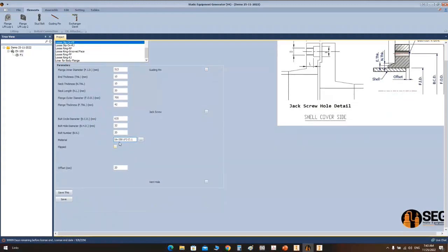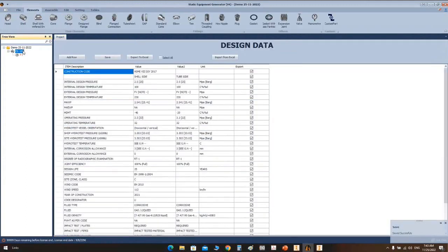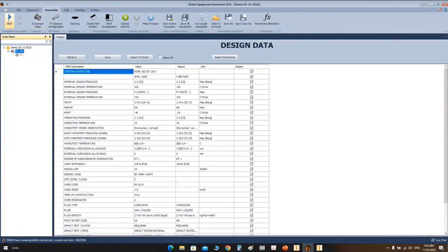Something like that. You can directly write it. Okay, and the offset will be at 0. Let's click on save. Now let's add another item, which is a linear body flange. It's something like a gasket, but it's made from metal, and it will be welded to the next item. So let's create this item first.